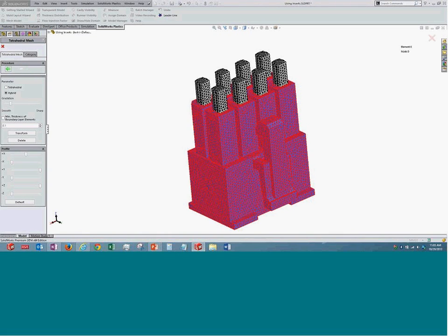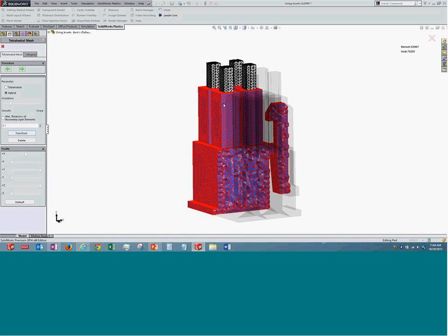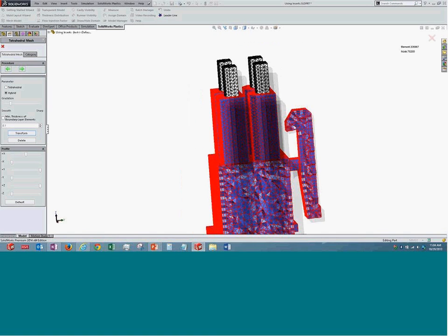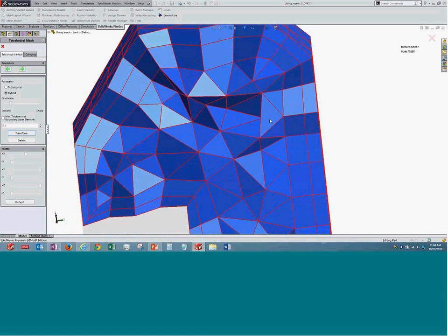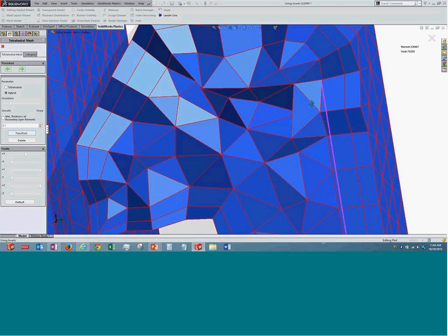I click form, to convert all this mesh into a hybrid mesh. It is already done. Now it is showing the result across a cross section, so it will zoom in at a certain location over here. If there are two layers over here, they are prisms, triangular prisms, the size of a triangle, and they are extruded, and internally they are all tet elements. So in plastic, if we want to capture the boundary layer accurately, then with this option we can capture it in detail. We can also specify the thickness of this particular boundary using this option over here.